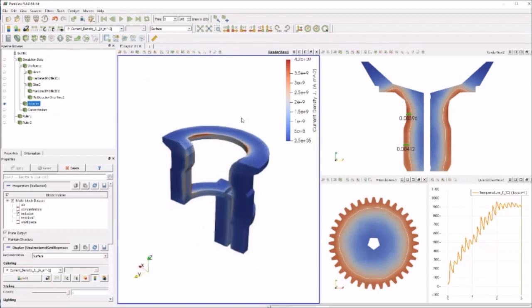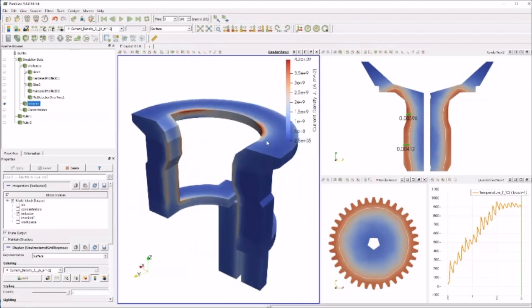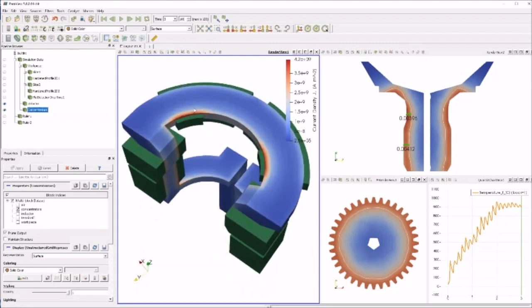In case of current density, you can clearly see here two hot spots. That could be potential failure points of the inductor. In order to make a design decision, let's look at the concentrator, and here we go. We see that the flux concentrators are just next to these hotspots. Clearly, while designing the concentrators, we would probably like to avoid this kind of design, in order to be sure that our inductor will not be heated to critical points and will not be affected by concentrator design.